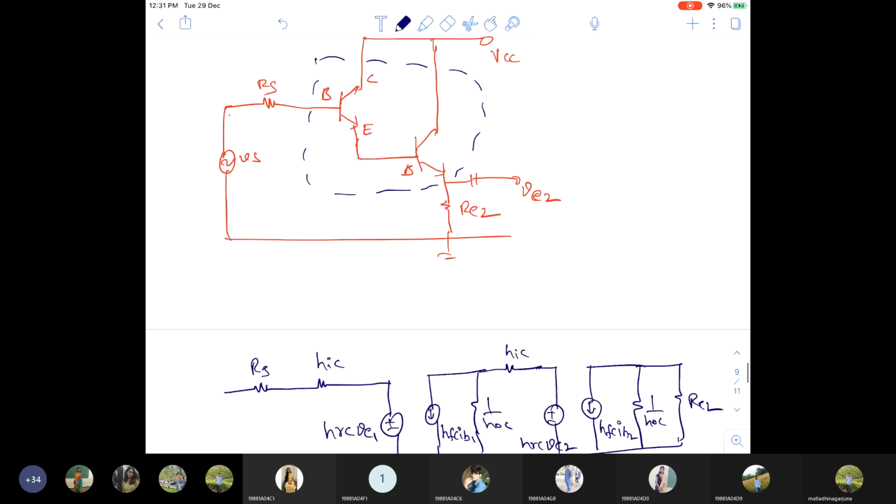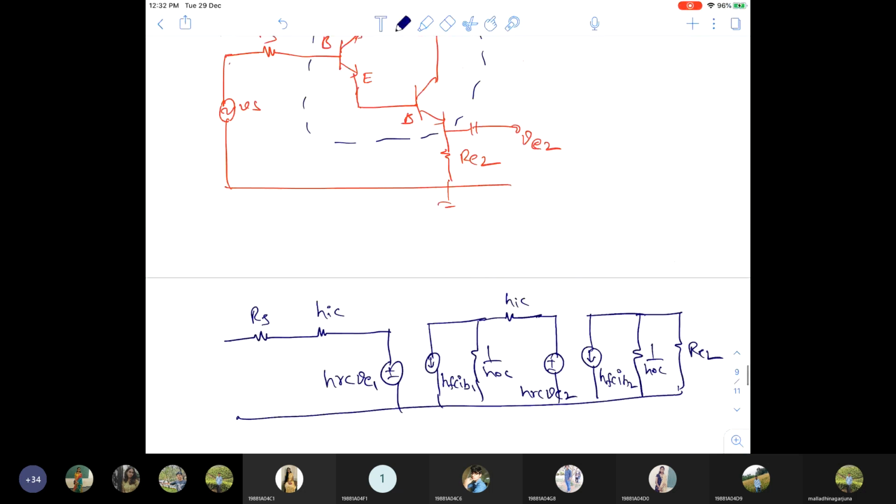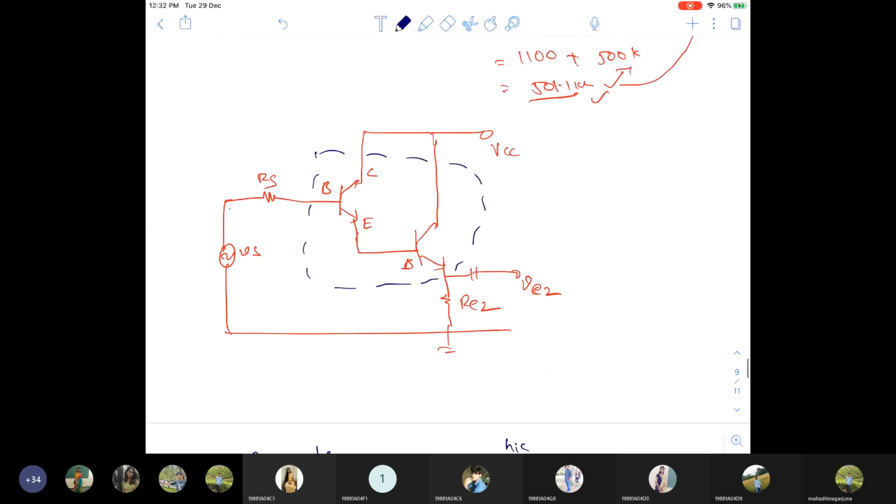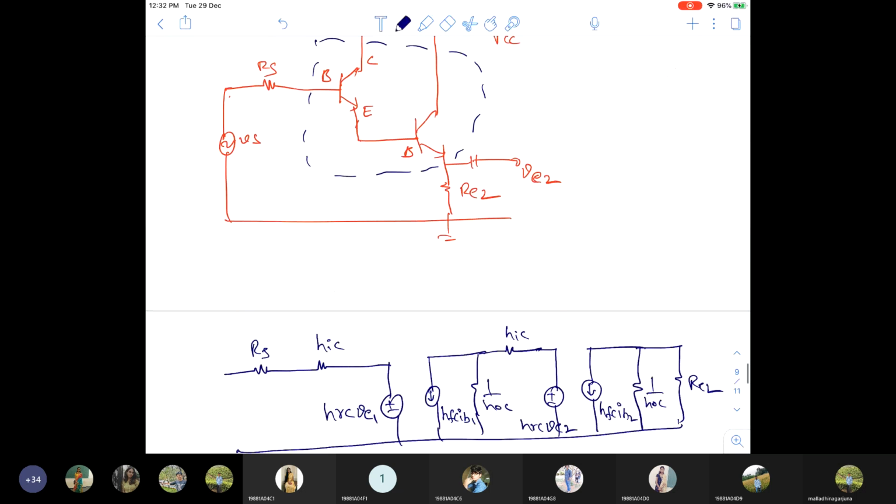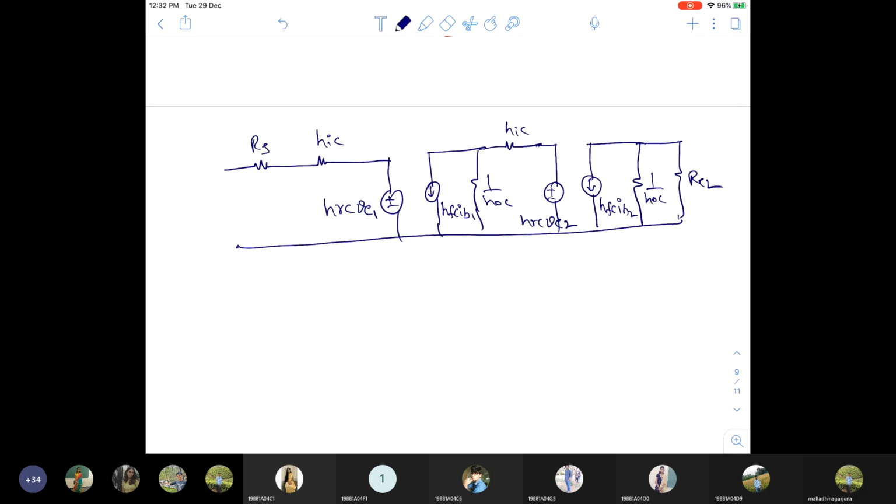So the remaining everything is in terms of, even there is no intermediate resistor between the first stage and second stage also. Here generally we'll have RC1 resistor in between, but in this case there is no resistor, directly coupled.